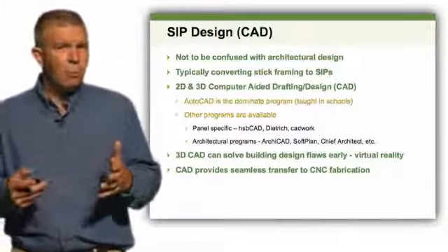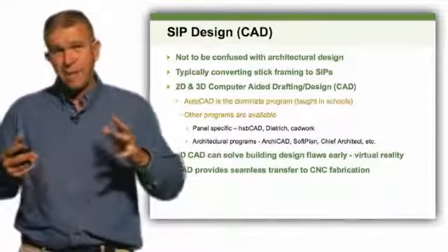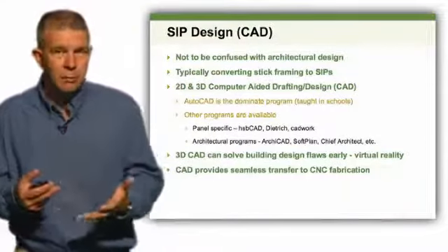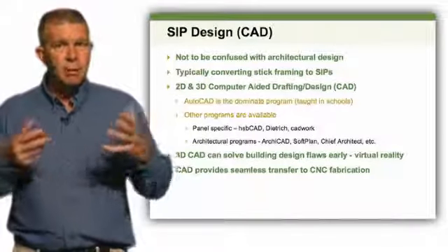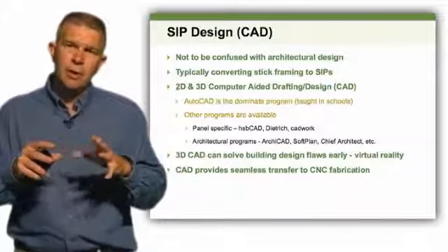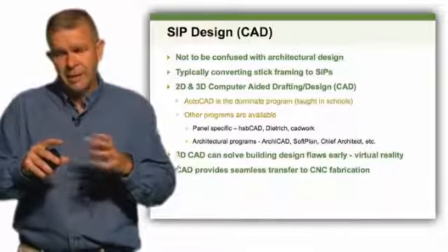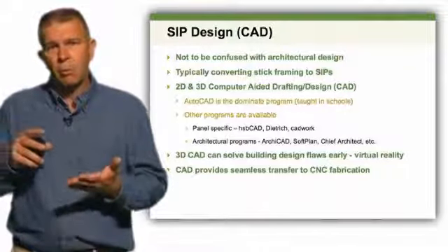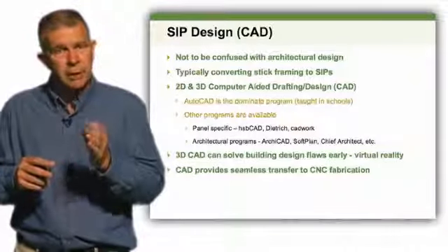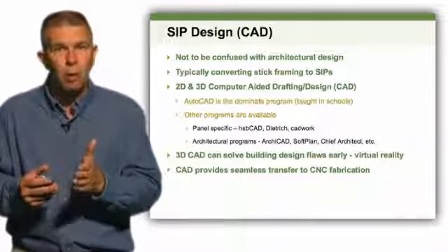The 3D CAD also does a very good job of catching complex issues as it relates to fitting the panels together. If you think about the thickness of a panel and complex roof joinery, when we design a building in a 3D virtual environment, we can figure out how these panels will combine properly when cut in a CNC environment. Because of the panel thickness, with compound angle joinery or compound cutting, you have to be dead on the saw angle to incorporate complex hips and valleys so that they come together and the joint works perfectly.